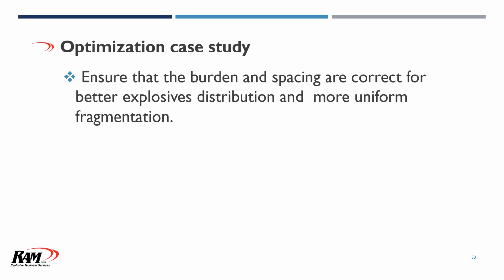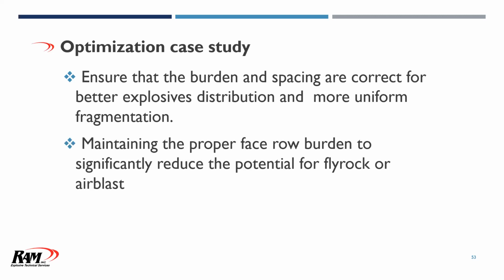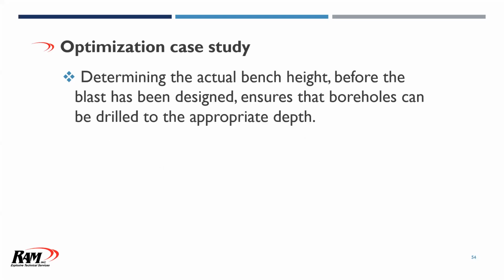There was no guesswork, laying tapes out and things like that. And right away, they started to see improvements in that. Significant reduction in fly rock and air blast, much more uniformity in the fragmentation right off. Along with that was making sure that the holes were drilled to depth. In some areas, they were too low. Other areas, they weren't deep enough.